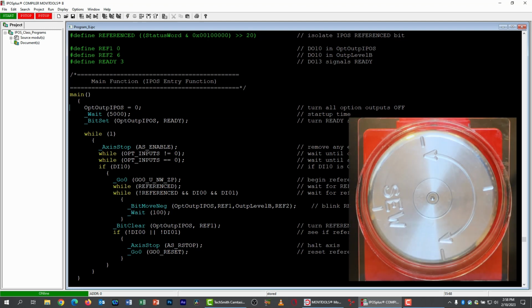We'll go to our control box. We will turn on controller inhibit and enable. We'll start referencing up, and then we'll try various possibilities. We really need to test 3 of them. We need to check for a normal referencing. We need to check for an early stop with controller inhibit and an early stop with enable. Let's give all these a try.